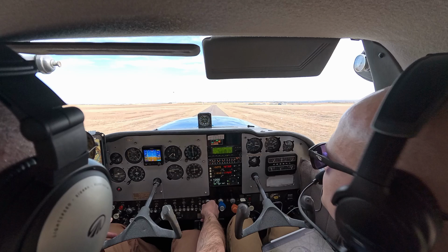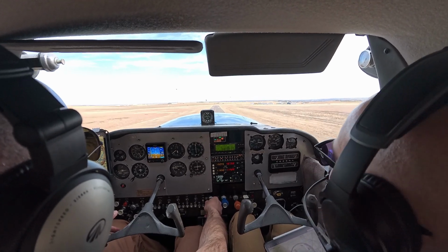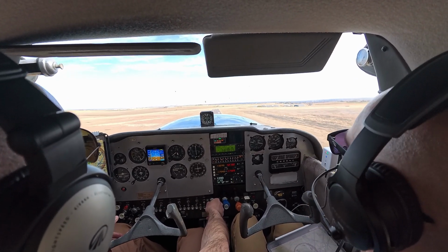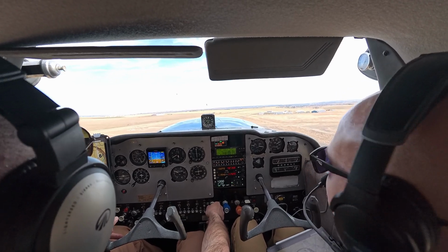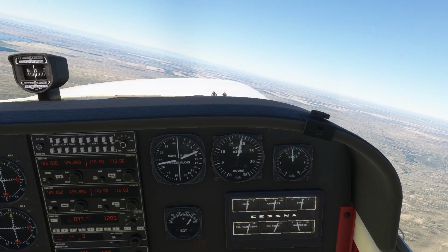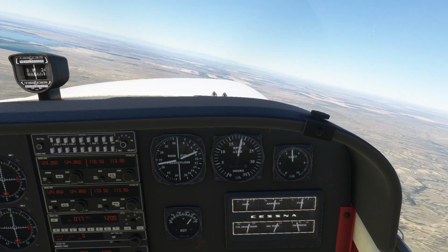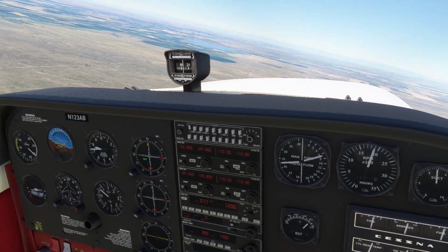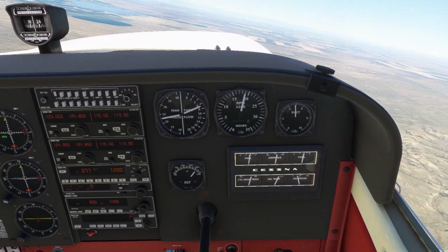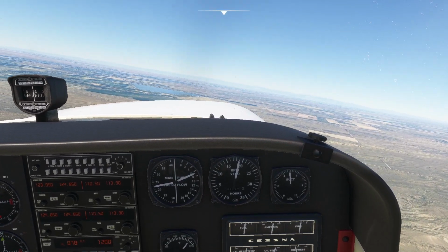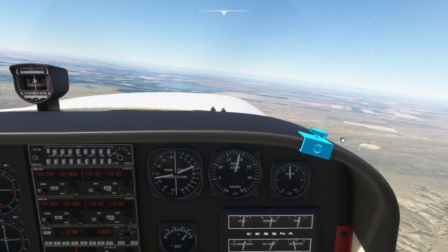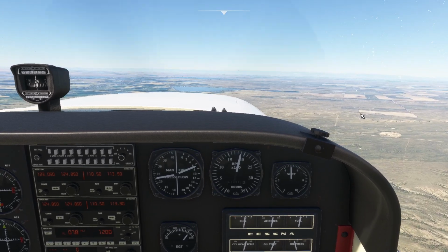Having high manifold pressure means you are increasing the fuel-air mixture going to your engine. This increased fuel-air mixture is producing more power inside the cylinders. If you were to operate with a high manifold pressure and a low RPM, the low RPM is adding resistance to the engine movement. In other words, high manifold pressure, low RPM has the airplane fighting against itself.